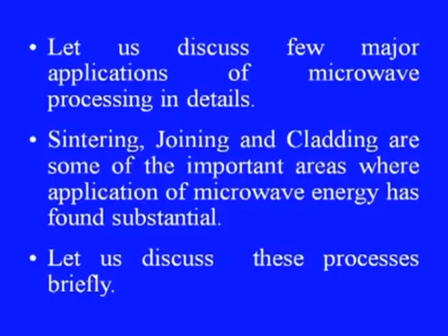As most of us know, the pultrusion process is mostly used for processing of polymers or polymeric composites. So, along with this pultrusion, we can use microwave energy where the material will get cured almost simultaneously.